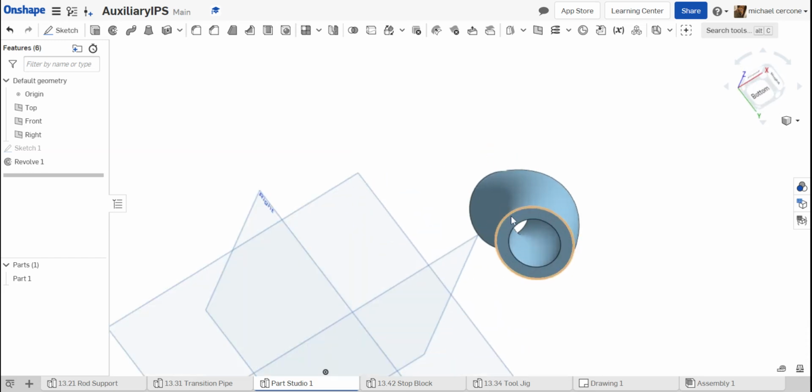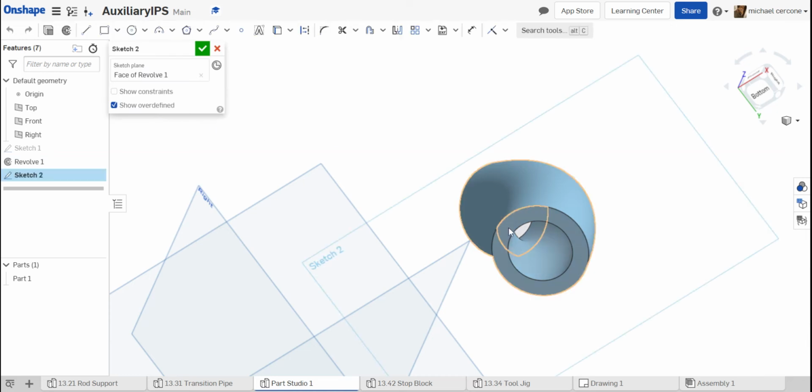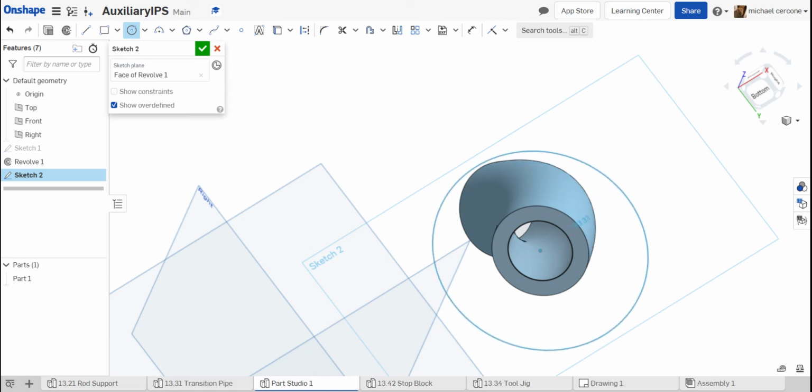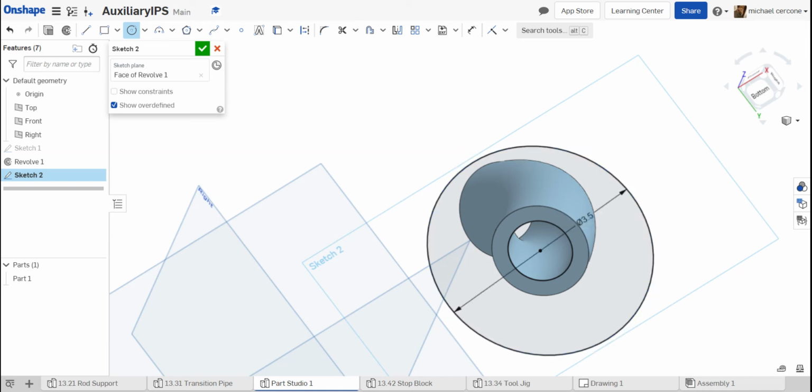Now I can start my next one on the bottom or the top. So I'm starting my sketch along the bottom. I need this 1-inch circle. So I'm actually going to click on it and then select Use, Project, Convert to redraw that one and also give me the center. And now I need a large circle that's 3.5. I need a construction circle for the 4 holes. That's 2.5.